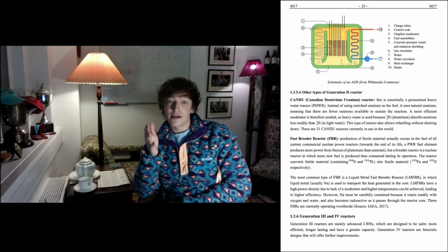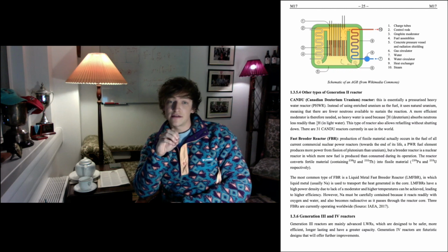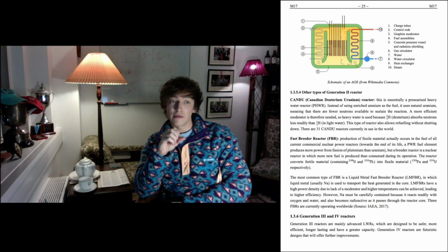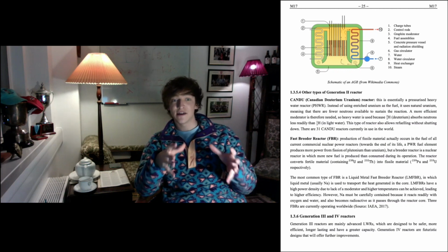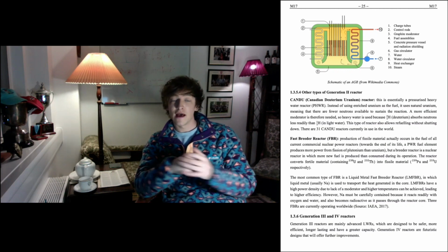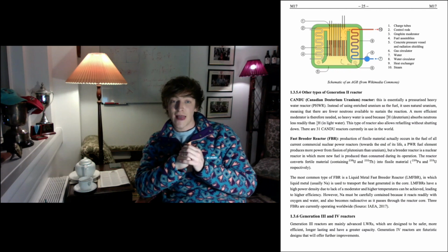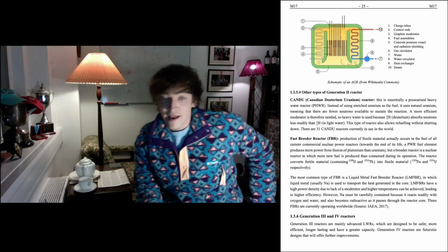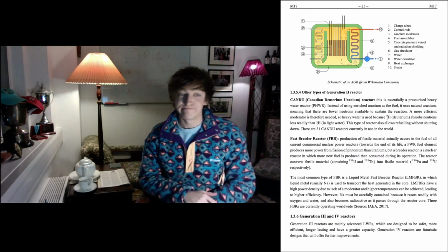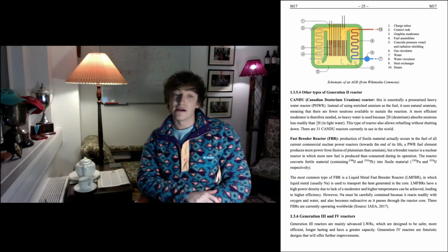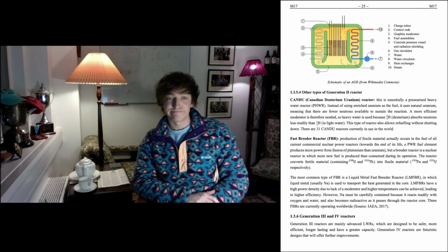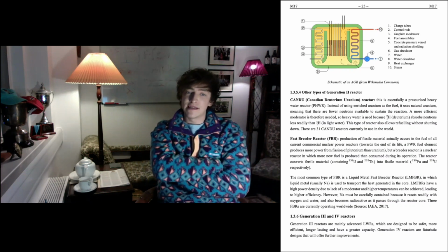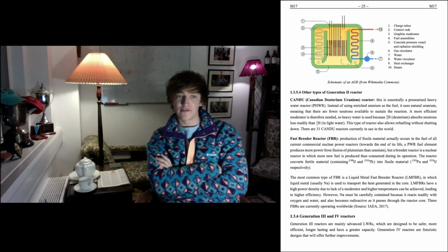Another key benefit is they use identical turbo generators to conventional coal-fired power plants, meaning that you can use identical tried and tested turbo generator plants in these reactors. But instead of zirconium cladding here, we use stainless steel. And instead of water being our moderator, we use graphite, just like the Magnox. So you can see that they've used that basic technology to develop these advanced gas reactors.